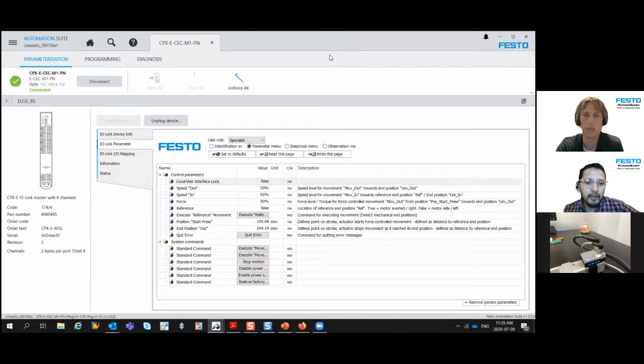Yeah, sure. So the SMS is a great alternative to pneumatics, especially in applications where you want to be able to accurately read current positions and run force moves, like force motion. Setup is simple. We can do it through the interface on the actuator itself or through IO Link directly. These parameters are stored in your PLC over IO Link. So if you ever need to replace the actuator, you only do it once. You just unplug the old actuator and then you can plug in the new one.